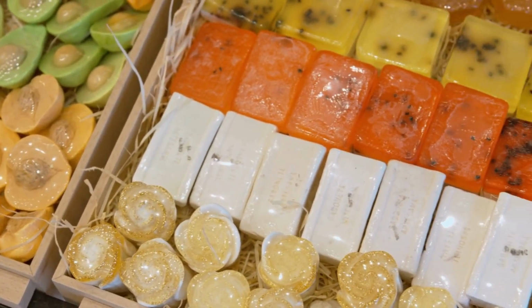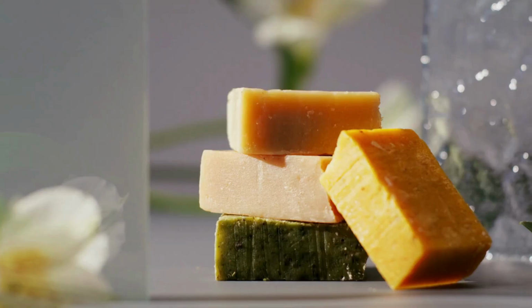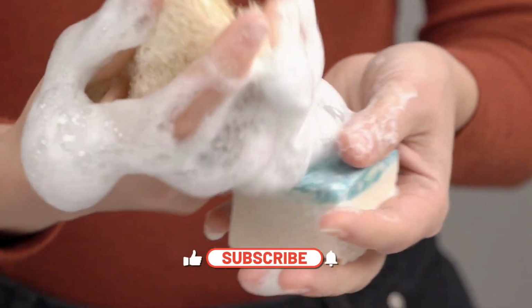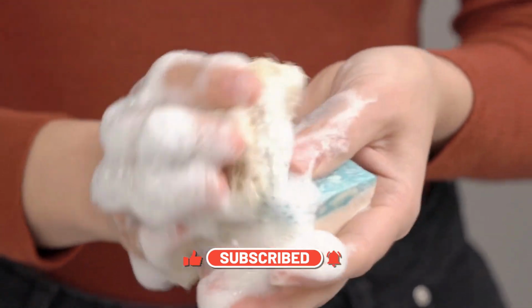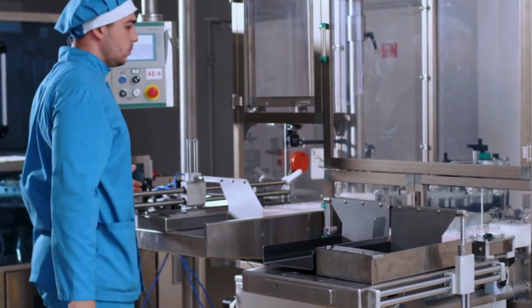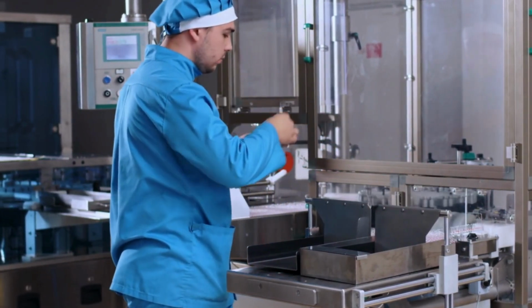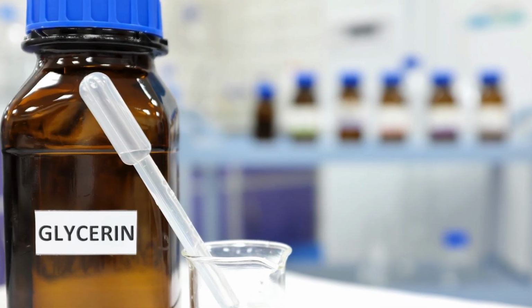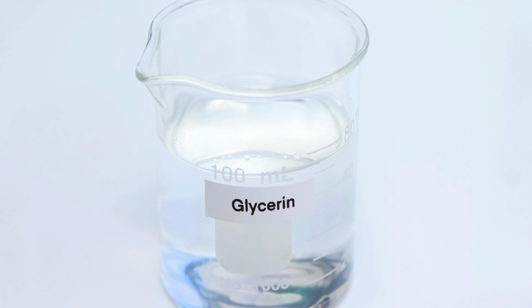But how is soap made nowadays? And what are the raw materials used? Soap is made through a chemical process called saponification, which involves mixing a fat or oil with a strong alkali, usually sodium hydroxide, also called lye, and water. In factories, they often use a faster process, sometimes using continuous saponification or adding synthetic detergents for extra cleaning power. Glycerin, which is formed during soap making, may also be extracted and sold separately.